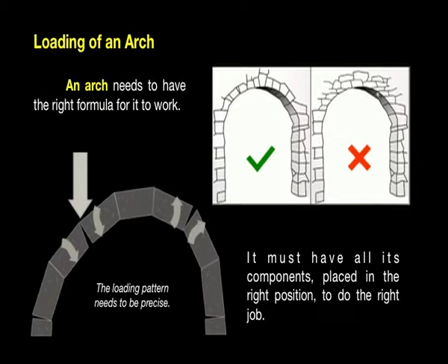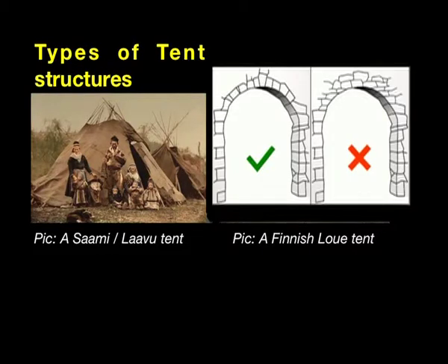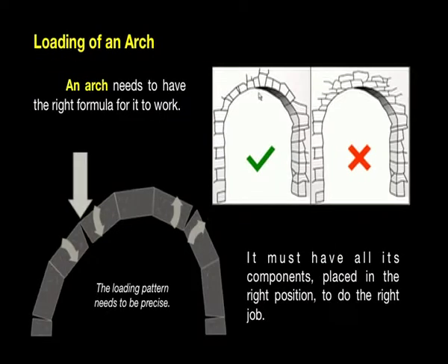So, all these individual stones are left individual. They do not correspond to any complex system, which means that they can buckle and fall under their own weight. This is typically a wrong way in which an arch is constructed, whereas this is the way an arch needs to be constructed.